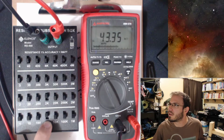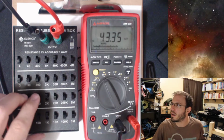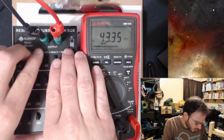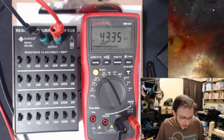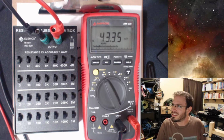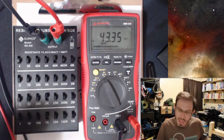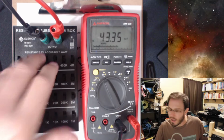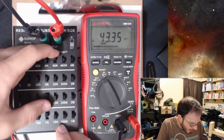And where's that 0.35K coming from? All of these are down. Okay, that 0.35 must be coming from wires or some error in the measurement accuracy. These are 1% resistances. But let's put all of these down.